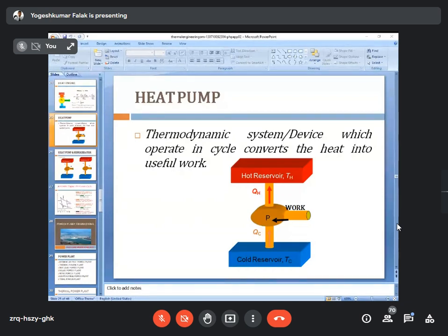Then your next statement, in kilojoule per hour, is that the COP of the heat pump is 1.5. So write down in the given data this quantity also. The house is losing heat at the rate of 60,000 kilojoule per hour, it's given. Also write that the heat generated in the house is 40,000 kilojoule per hour, it's also given.